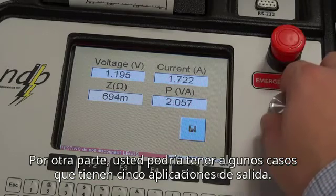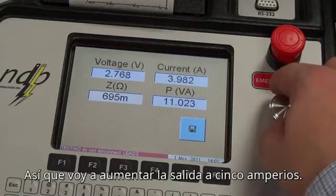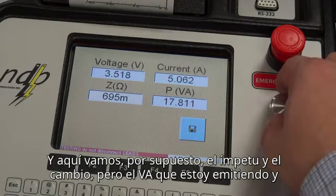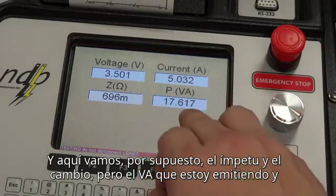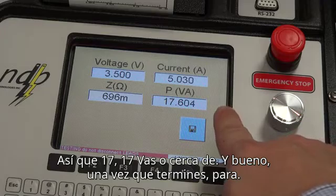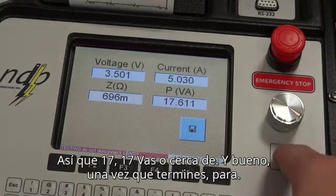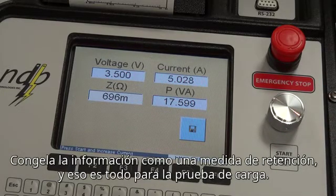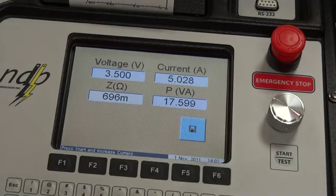Then again, you might have some CTs that have 5 amp output. So I'm going to increase the output to 5 amps. And here we go. Of course, the impedance didn't change, but the VA that I'm outputting and that this circuit is being able to see is much higher. So 17 VAs, or close to. And once you're done, press stop, and that's it. It freezes the information, kind of like a measurement hold. And that's that for burden testing.